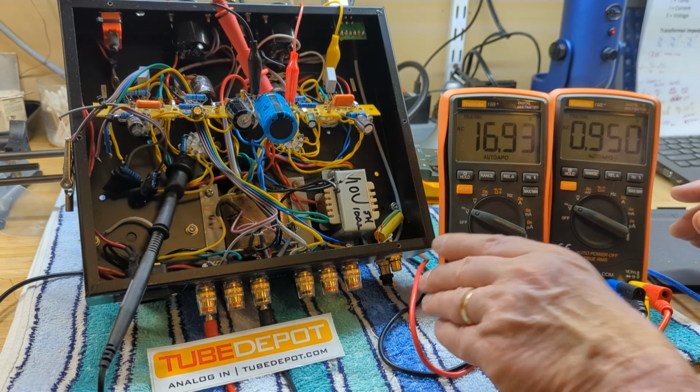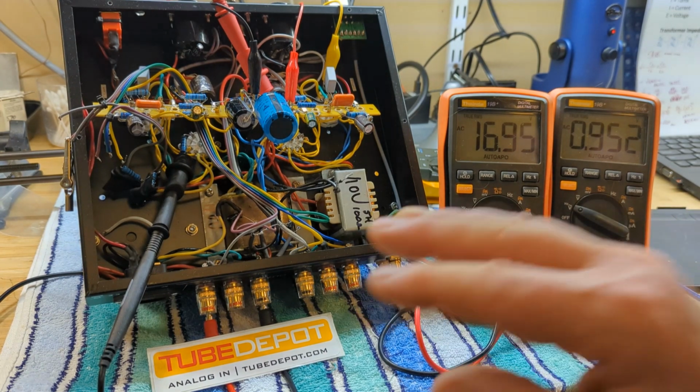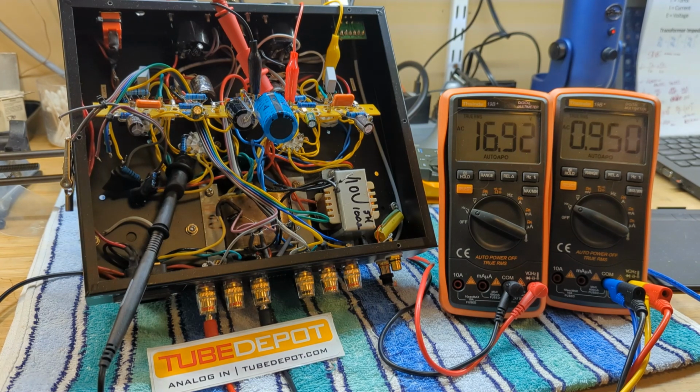Well, maybe we'll step it up and get a little darker. Okay, that's good. So we're in the 8 ohm output. I know that I want to get a nice strong signal into it, so we're going to emulate an 8-watt signal coming out of that transformer, and an 8-watt signal onto an 8 ohm resistor is 8 volts. How nice is that? So let's turn her up to 8 volts and see what we get for a primary voltage.